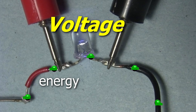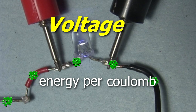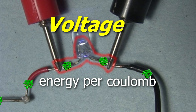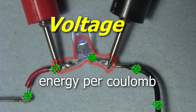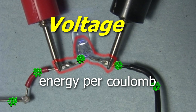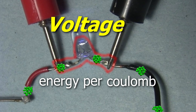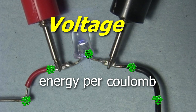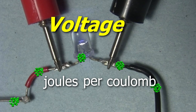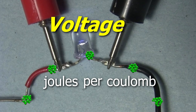Voltage is the amount of energy that's used to move each unit of charge, each coulomb, from here to here. That's why we put the meter probes on either side of the diode, or whatever we're checking the voltage of. Voltage is the amount of energy used to move each coulomb of charge from one side of the diode to the other side. While charge is in units of coulombs, energy is in a unit called the joule. 1 unit of energy is 1 joule. So voltage is in units of joules per coulomb.